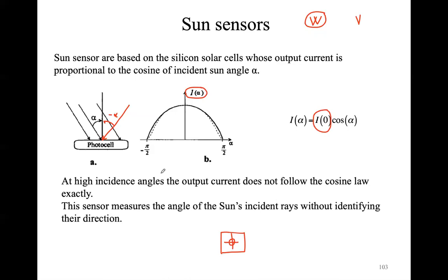The first advantage is that you can use sun sensors for many different missions because you are able to see the sun from different parts of the solar system. And so you are able to get attitude information for multiple types of missions. That's really a great advantage. The other advantage is that you have better accuracy compared to the Earth sensors.